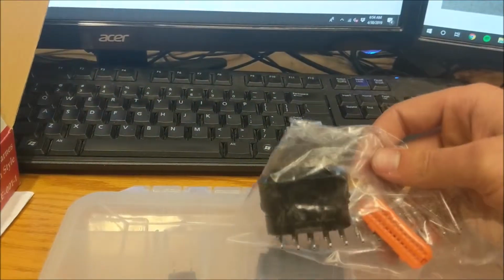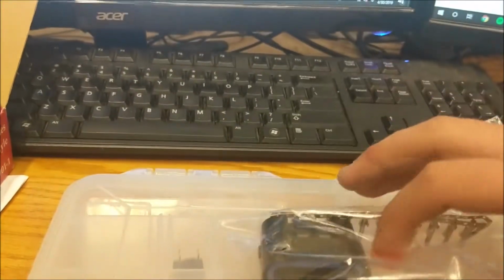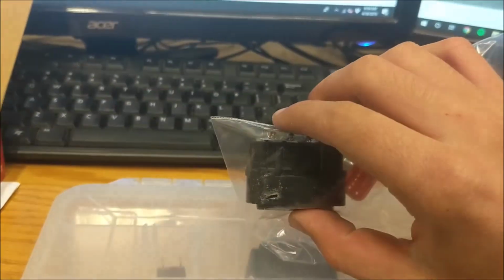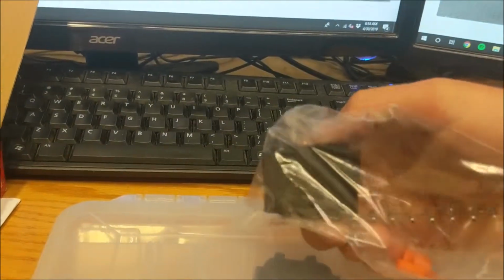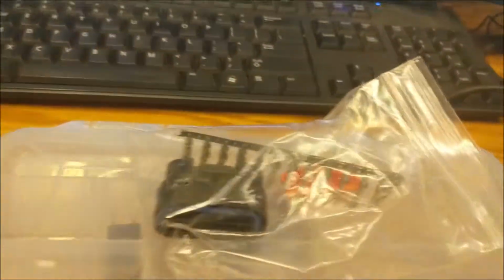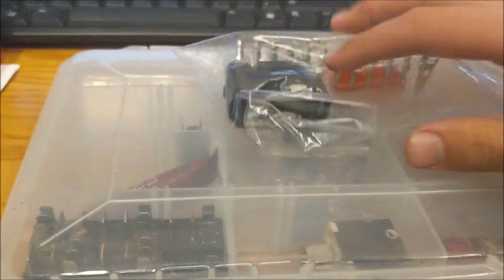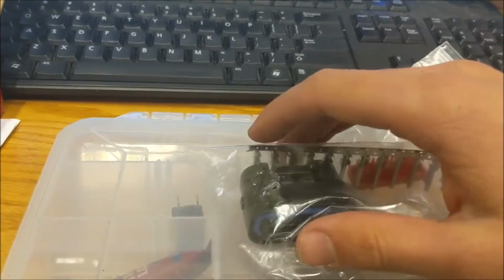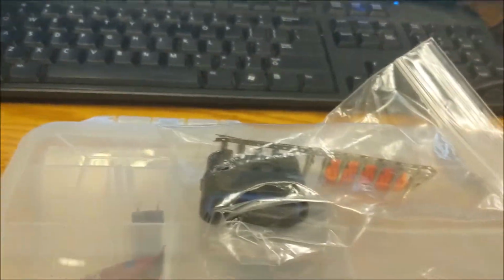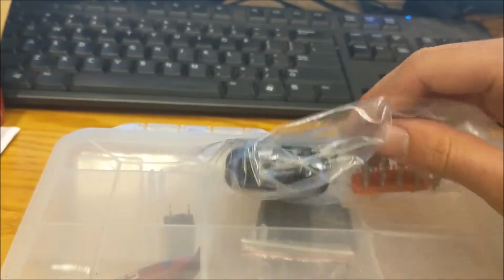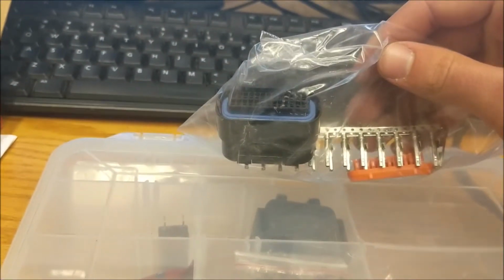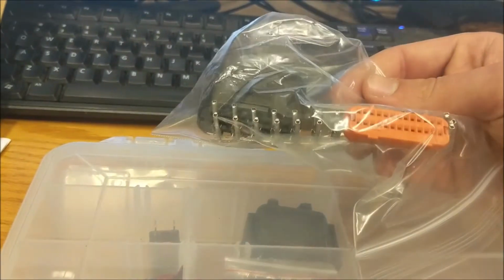This is a connector from the PE3 ECU. This connector is an integral part of your sensor and controlling system on the formula car. Common problems with this connector are mispinned wires and loose wires. To better combat this, be sure to check the PE3 connector and make sure each wire is firmly clamped in each of the pins.